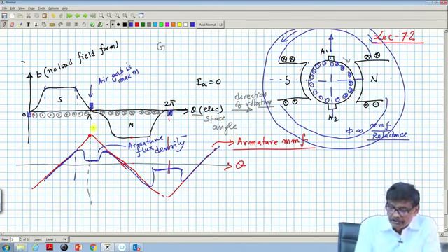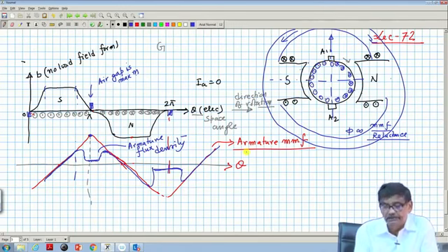So, drawing of the red curves is very simple. I know the armature current, and there are many conductors which are almost uniformly distributed. The peak value will occur here. Why I have put plus: because for the south pole I have put plus. So, these lines of force are also along this line; cross and dot will give this line. So, positive, you draw it and get this, that is the whole thing.